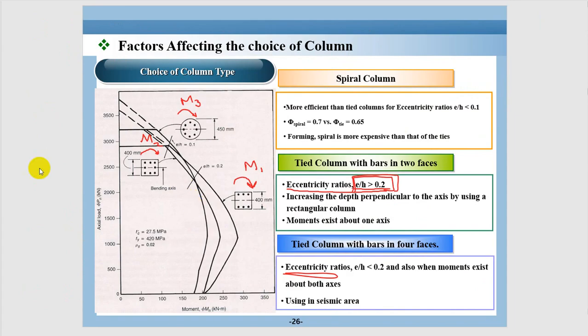So here, when you have two layers of rebars, you can distribute rebars as far as possible horizontally, because you have only two layers, then this column is good for large eccentricities over 20%. Whereas you have here the circular one. In the circular column, the rebars are very limited. You can't go that far because you have to go back, right? So your rebars are concentrated.